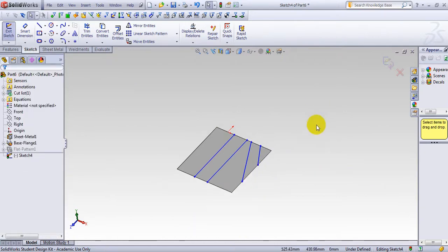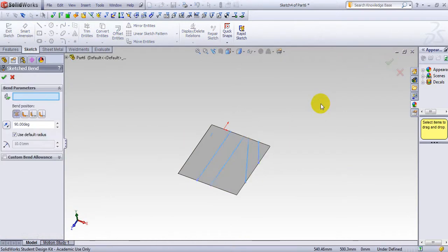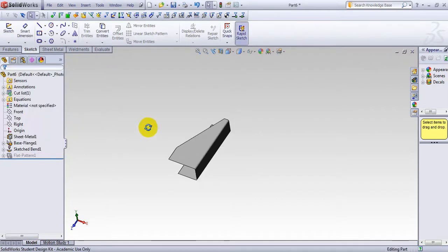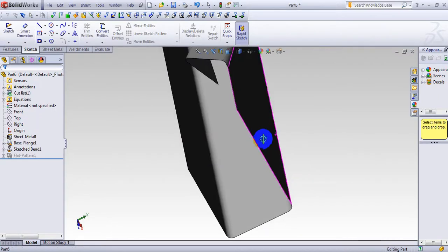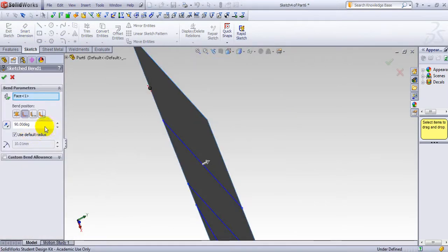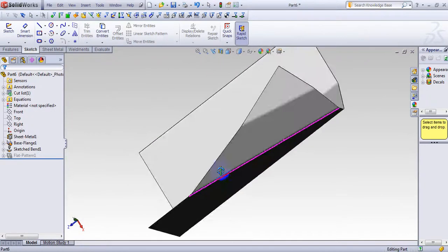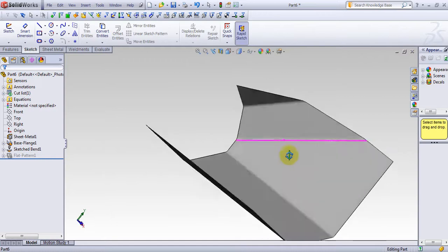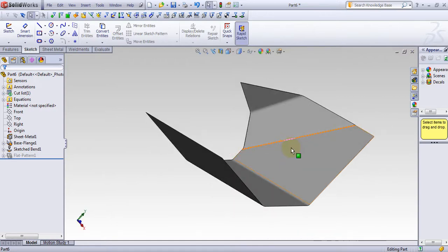So now I made these 4 lines, and now I want to bend it here. So simply I can use this, and you can see there are other options here too. I can choose the angle, or I can choose the radius, and the outcome would be a simple fold, and I can see that I fold these things accordingly. Now I can go simply here and modify it. I may not need 90 degrees, I need 45 degrees, and in that case, of course, it would be something like this. You can easily make basic origami shapes using these features.